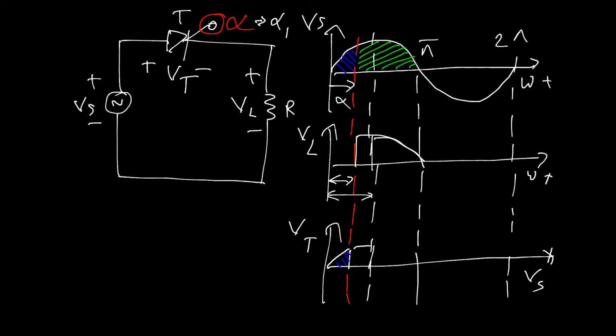We know a thyristor can be switched off by reducing the anode current below the holding current, and that can be done by applying reverse biasing across the thyristor. The same thing can happen by using this kind of AC signal. After crossing pi, the current is 0, and we are still applying reverse biasing as in a normal sine wave.